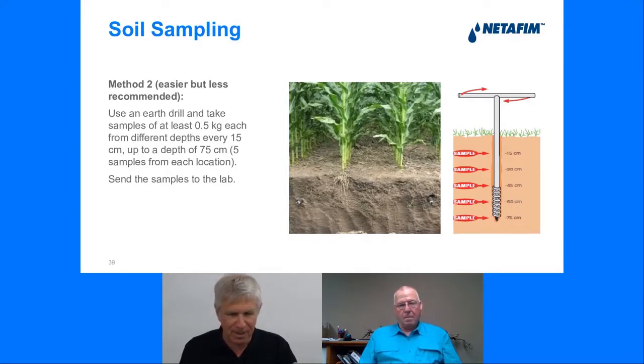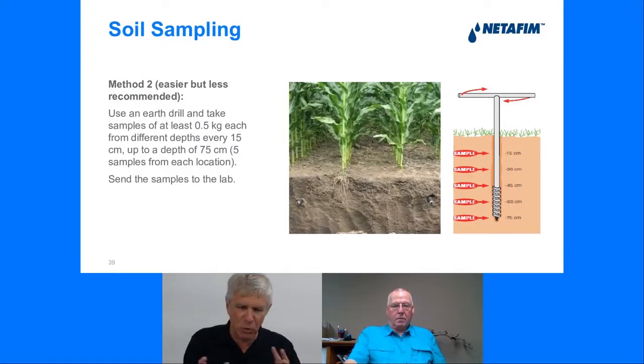Take it into consideration. Another item you can see over here, 2 laterals. This is a cornfield. During the growing season, it's connected, and we follow the irrigation requirement or the irrigation pattern. So we flag the location of the laterals and we put soil moisture sensors over here because we assume, and I think it's a good assumption, that for 2/3 of the growing season, when speaking about corn, most of the water and the nutrients will come from the drip irrigation. So the roots are going to be located close to where the lateral is. So if I'm placing a soil moisture sensor over here, it's going to give me a good estimation of the water status in the soil.